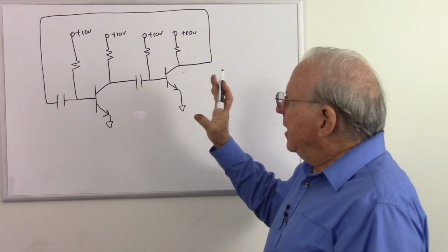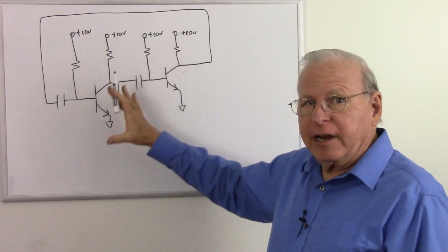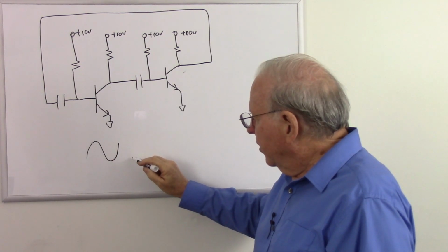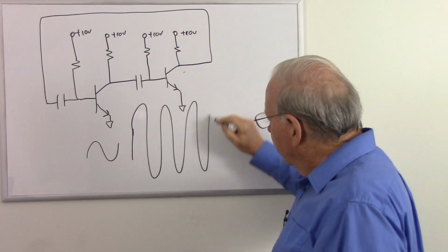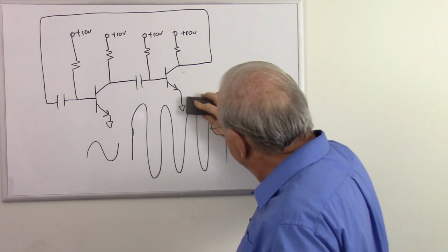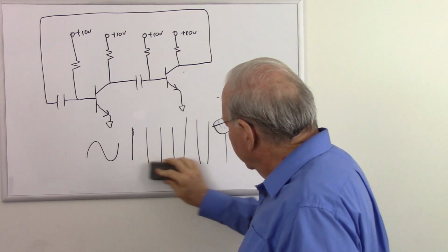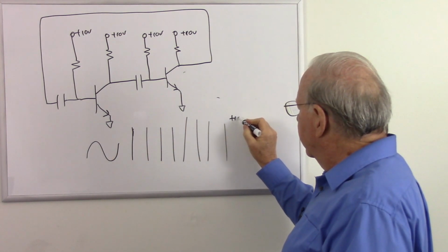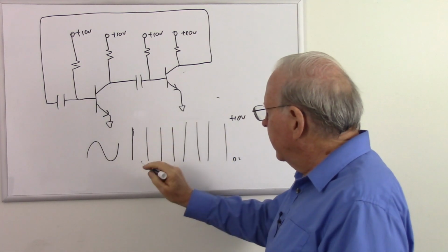But because we have very high gain, we're just going to saturate every cycle. So instead of getting a sine wave, it's going to get a big sine wave. I'm going to draw it really big here because what's going to happen is it's going to hit the voltage rails, because it can't go below 0 volts, can't go above 10 volts. So there's plus 10 volts, there's 0 volts. Clean that up a little bit here.